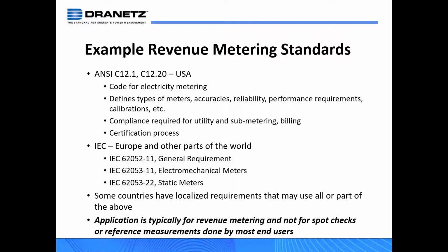So when money's going to be associated to that, typically they need to be revenue certified meters. And that's typical around the world, you know, regardless of what metering standards you follow. And there is a certification process for that to verify that the meter is doing what it's supposed to do. So we move over to, in Europe, the IEC, the International Electrotechnical Commission for Europe and other parts of the world. They have their own versions, very similar, but they are a little bit different to the ANSI versions. And it's the same methodology to make sure that not only the meters are working right, the accuracies are right, the reliability and performance over the entire system is there.